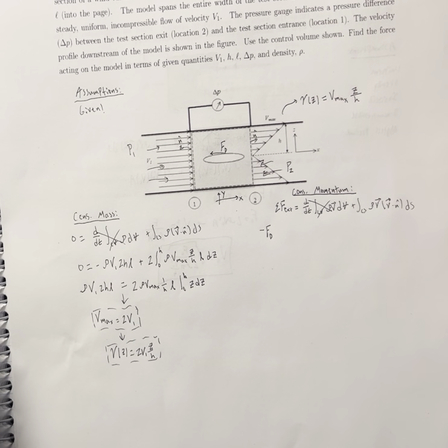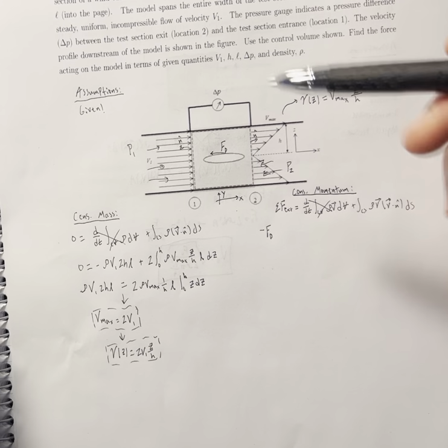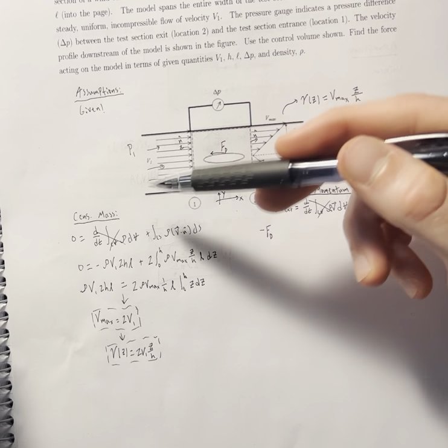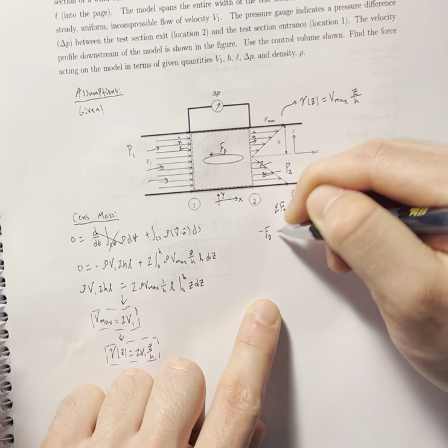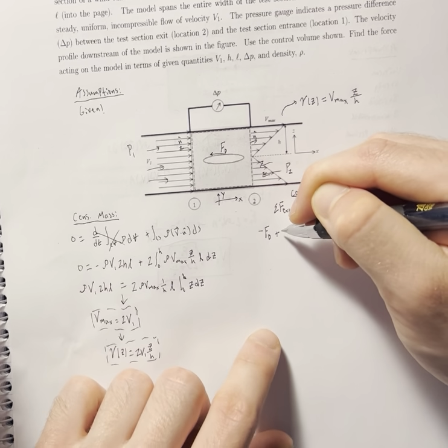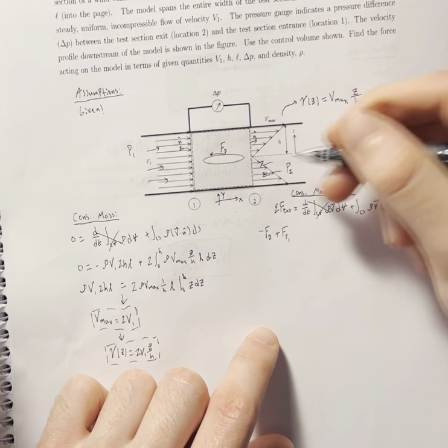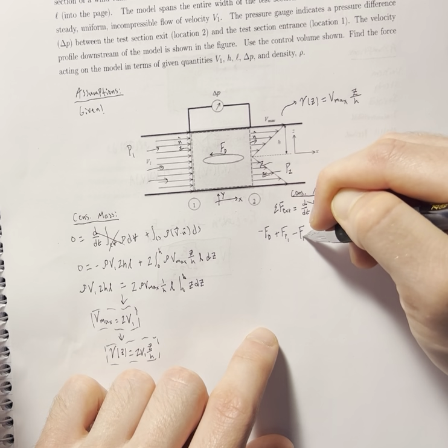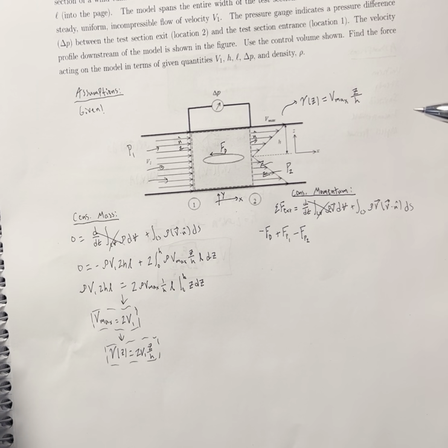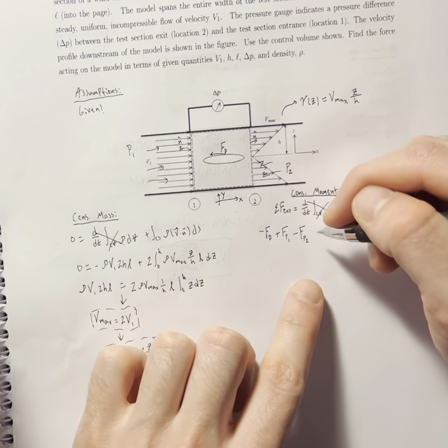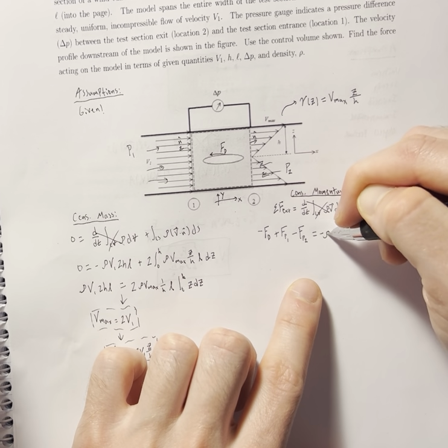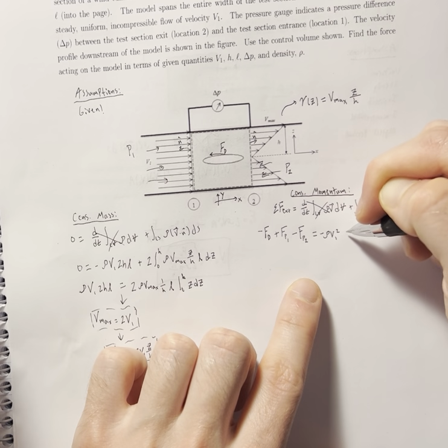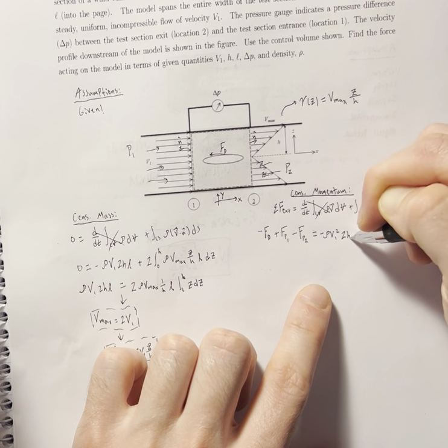For these, we're not dotting anything, right? Literally, what direction are these pressure forces acting? In the case of P1, it's just in the positive direction. So plus FP1, and then the opposite is true for the second one. Boom. Easy as that. And what's a pressure force? It's just pressure times an area. So I'll do that in a sec. But let's keep simplifying. For this inlet, it's easy enough. It's going to be negative rho V1 squared times A, or 2HL, whatever.